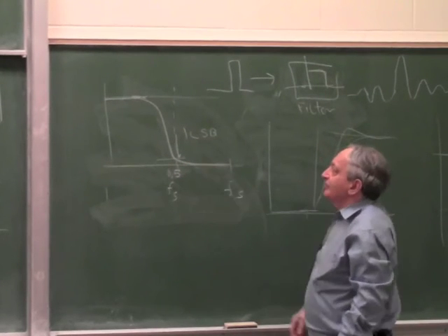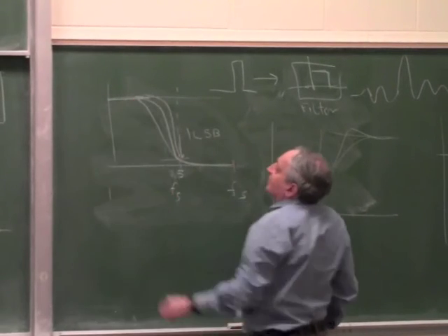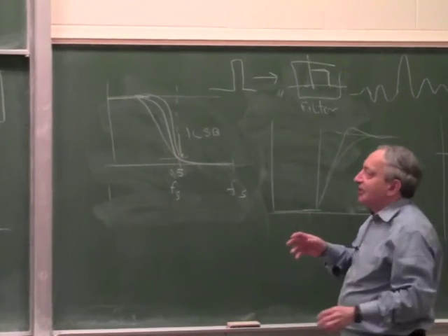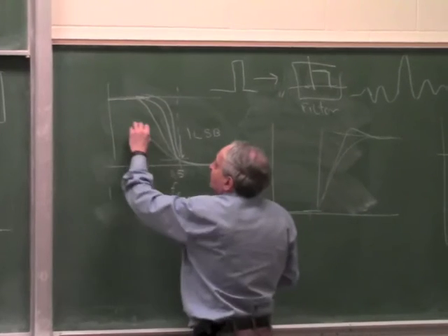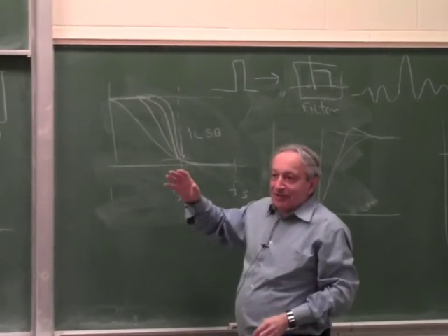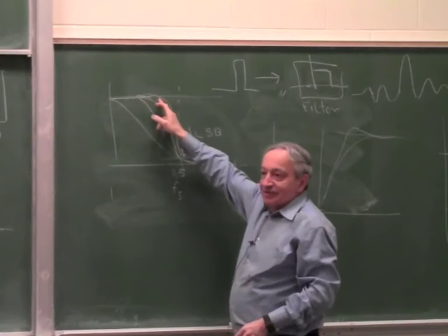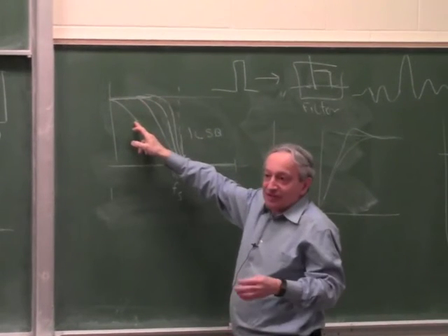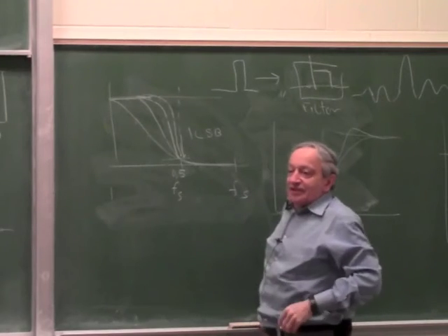Any one of those filters will be acceptable, and then there is a trade-off. The trade-off is basically loss of speed or information. If I take a filter like this, it means I'm slowing the system down, because I can't move at this frequency at full speed. But this is very good for phase and so on. So this is a trade-off in the servo design.